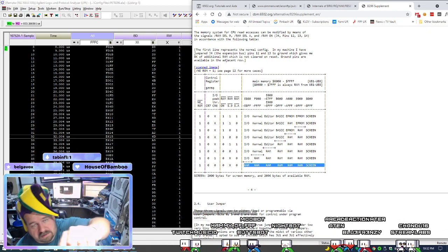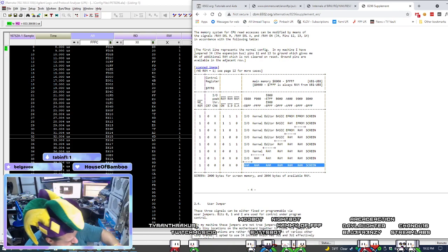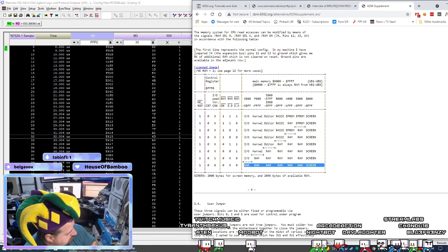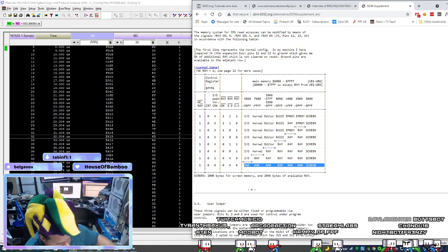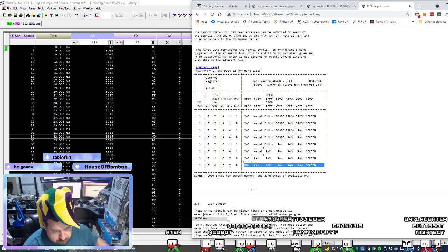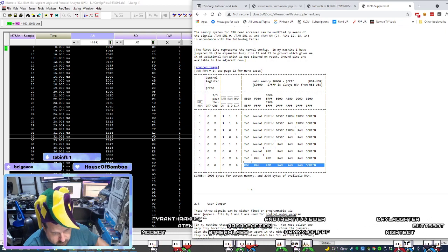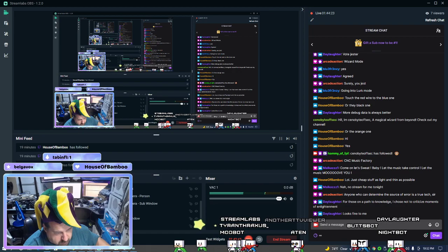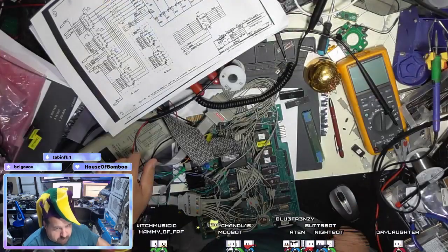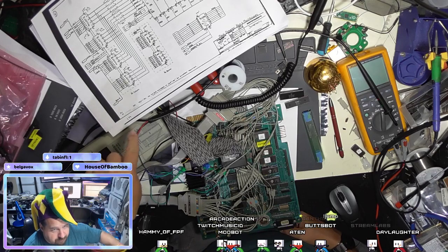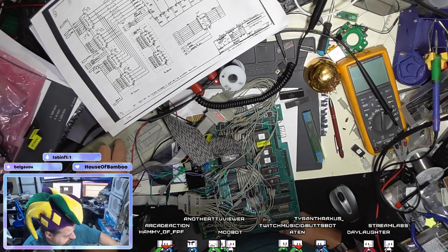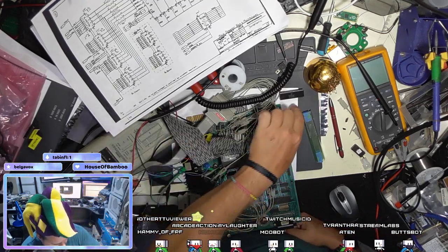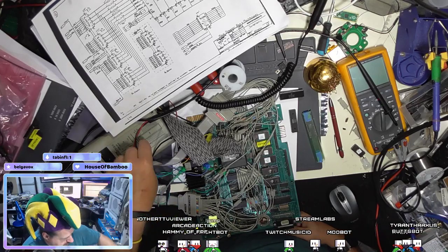So what I'm using is a Fluke microsystem troubleshooter. That's what this cable is here. It's basically emulating the CPU. It's actually not emulating the CPU. There's actually a 6502 inside. I need to get this thing hooked up. It's very annoying. So this box here has a 6502 inside it. It's actually got a CPU inside it, but it'll take control and emulate the 6502.